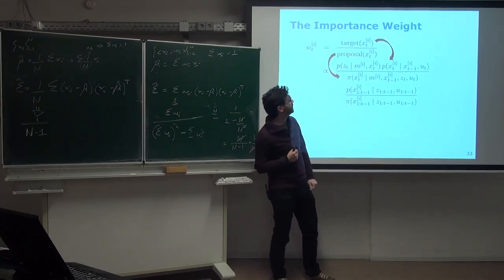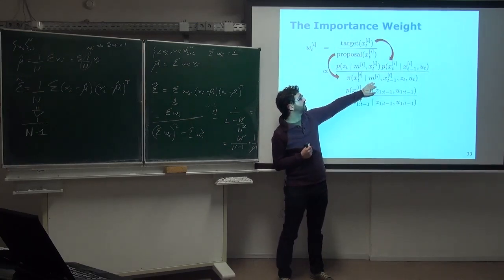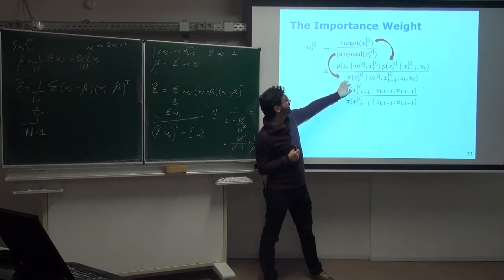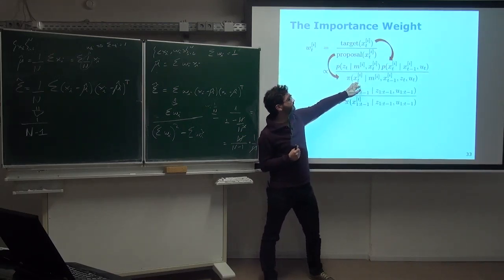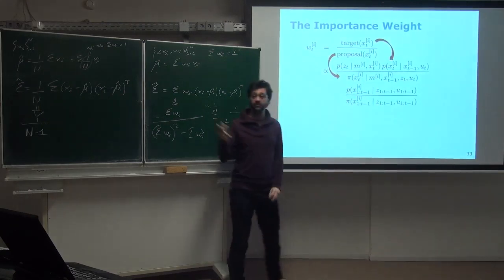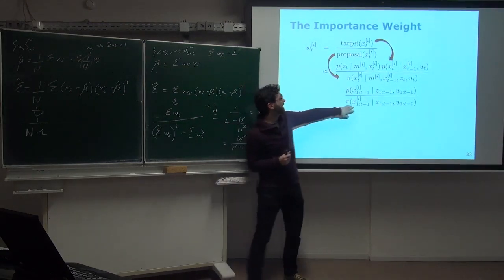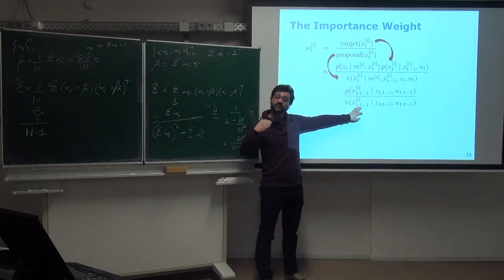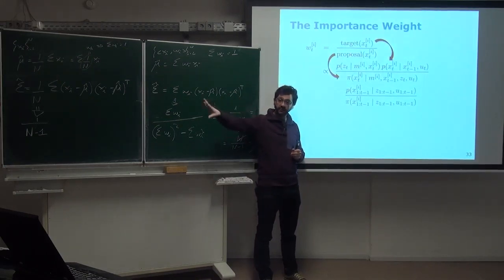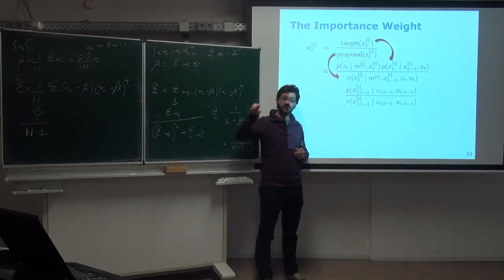If you look at our proposal, we have the distribution here, which is the proposal we want to approximate, which is x_{1:t}, the map, z_{1:t}, and u_{1:t}. That's what we've seen in the slides before, times the sampling that we have already done with respect to the previous time step. Because we have a part of the trajectory that has already been sampled, and we have it from before, and we are now sampling the last step, okay?